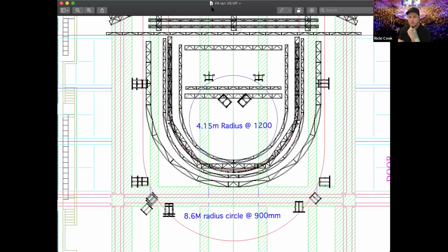where those subs are positioned is sort of as symmetrically even as possible from the main arrays to keep the time alignment as even as possible. So you're not having to do any crazy offsets and delays to try and time align the subs to the mains and keep the phase at the crossover point coherent around the whole room. Well, for as much of the room as possible.